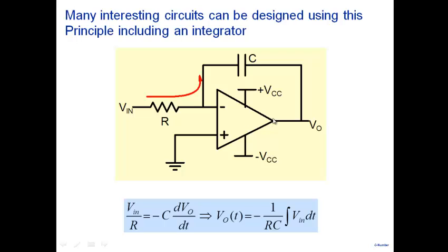The fact that, let's say, the input resistance between these 2 points is 1 mega ohm is not going to bother you. The reason is that even though the resistance between these 2 points may be only 1 mega ohm, the voltage at this particular node will be typically very small because of the feedback. So any current which flows here because of input resistance will not be very large. It's not going to bother you that much. Similarly, the output resistance being, let's say, 10 ohms or 20 ohms is also not going to bother you.